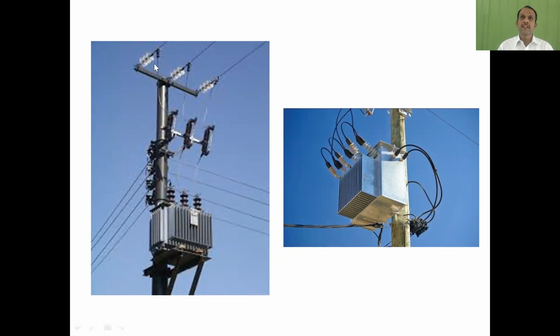You can see 3, which is nothing but 11 kilovolts, coming as input here, and it is going into 4. You can see the 4 wires, which are R, Y, B, N. So R and N is going to give 230, Y and N is going to give 230, B and N is going to give 230. So the single phase is produced from three phase, and there is a relation between the line voltages and phase voltages, which we will study in the near future. And this is also one of the examples of the distribution transformer.